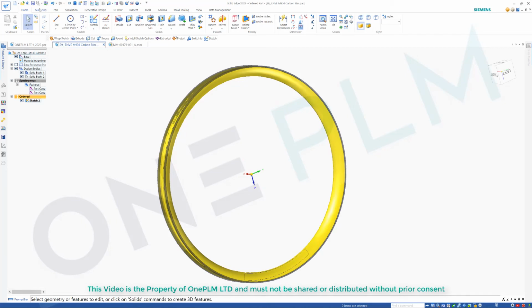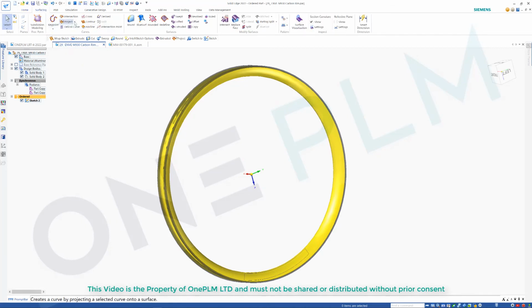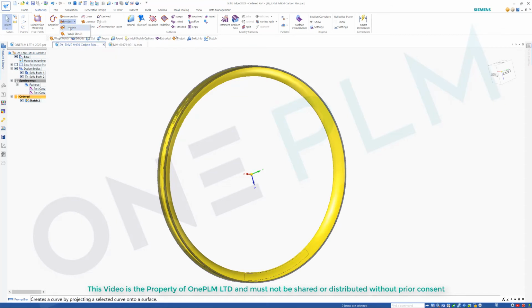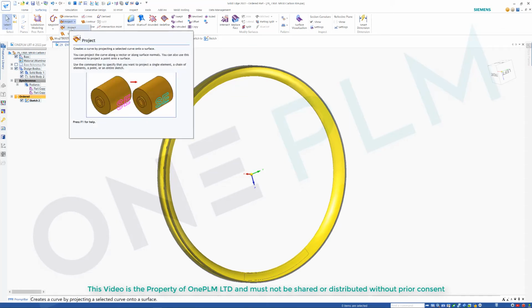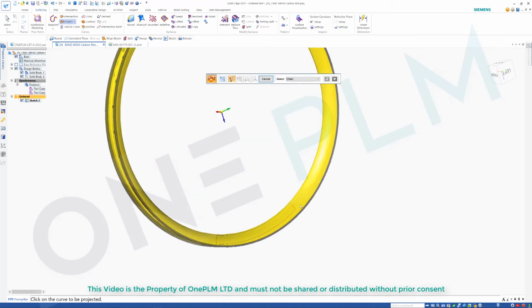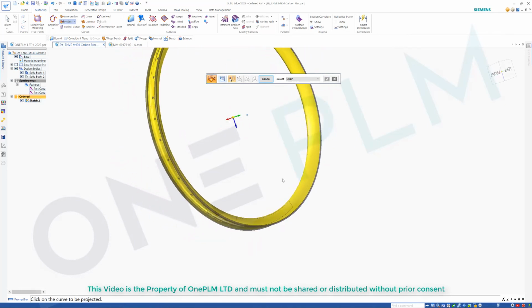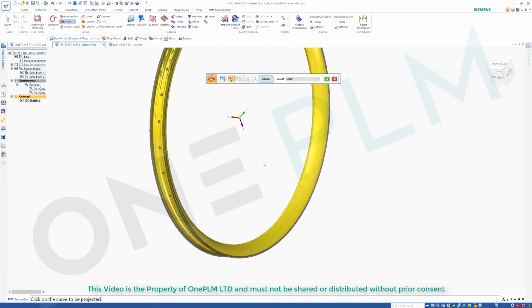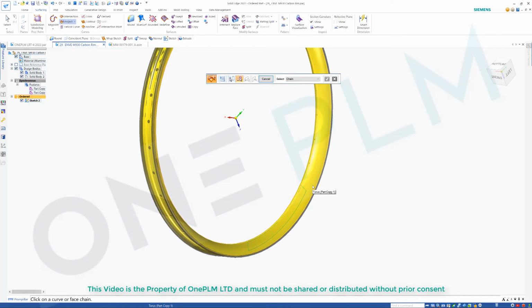We can then close that sketch. And we can now use that sketch with the tools. So we go to the Surfacing tab and choose the Project Sketch option on here. So we need to select the sketch that we've just drawn. Accept. And select the surface we want to go onto. So I want to select the torus surface on there. And then accept and left click to confirm the direction we want that to go.